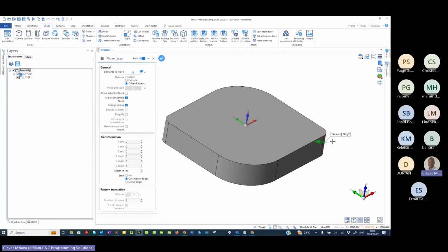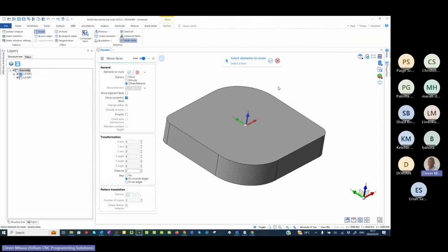From there, I can start moving my mouse pointer or the arrow that I've got. And you can see my fillets are changing dynamically on both sides, which I've picked. That's such a very good function or feature in this Designer. So I'll make that one 12 millimeter, enter that. And both of the sides have been dynamically changed.